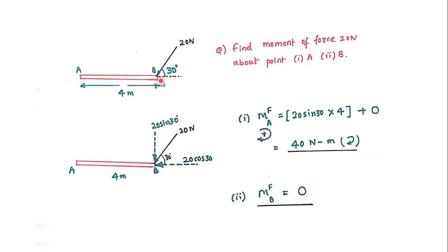So in the calculations where a non-concurrent force system is involved, and especially when we have to find the moment of various forces that are coming at an angle, meaning they are not vertical or horizontal, we resolve the forces into their horizontal and vertical components, and then we calculate the moment of those forces about the given point.